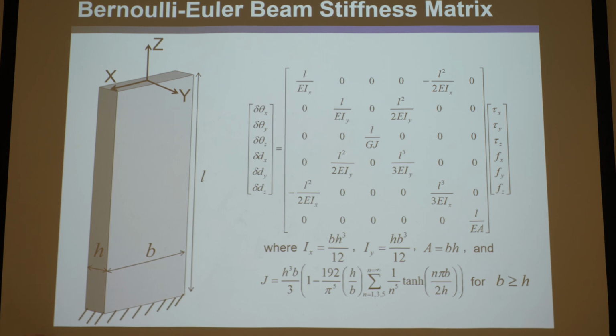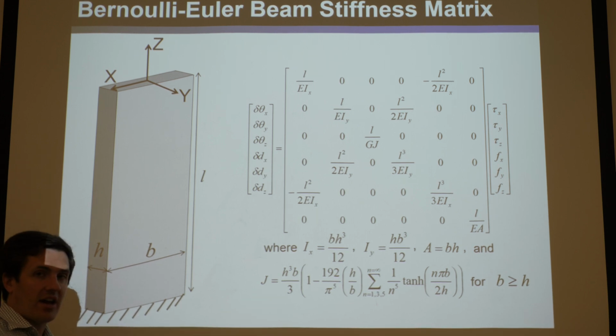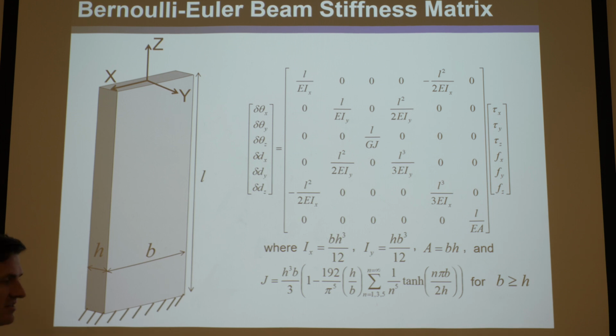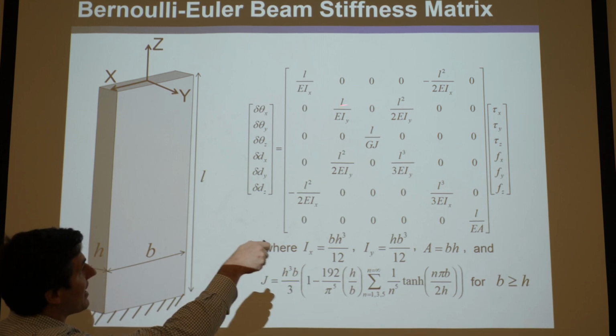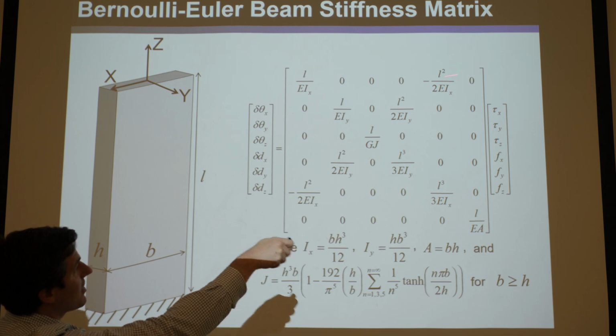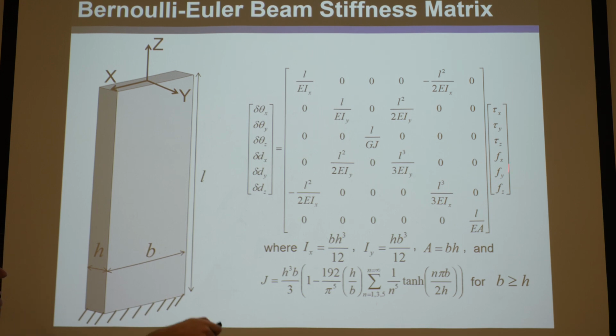So it's like if you plotted force versus displacement, it would be the very first slope of the plot. It's the instantaneous first slope of the plot before anything ever deforms is what we're really relating in these equations. That's the stiffness we're talking about, okay? But for very small displacements and for pretty small loads, they're a very good estimate, okay? Nothing's deforming large amounts, it's just infinitesimal, essentially. And like I said, the only ones of these that affect delta theta x is tau x and Fy. The other ones don't, so they're zero, and this one's positive and this one's negative, so it can sort itself out. So you multiply out, that's the first equation.